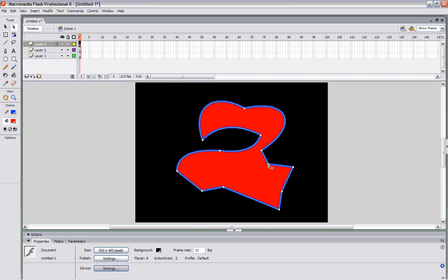If I come in here and I select this one, I'm not getting my selection like I do here because my pick boxes probably aren't being manipulated or aren't out there. And the reason they're not out there is because they're not curved. You only get these pick boxes on this side when you have a curve. Okay, so I'm not going to get the pick box on this side. Notice how I had this pick box, it's got two grips. Okay, this gives me the ability to compound my curve. This one only has one pick box because this is a straight line. So I only have the ability to manipulate that.